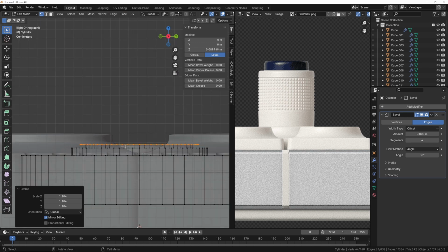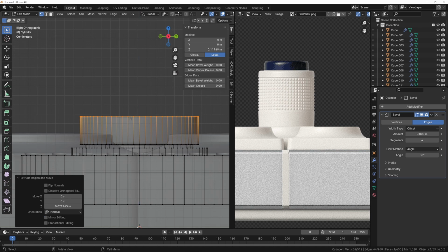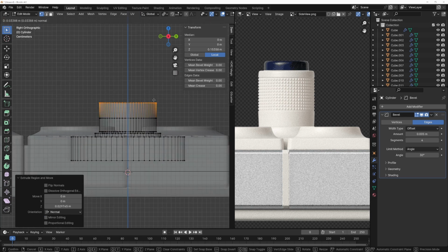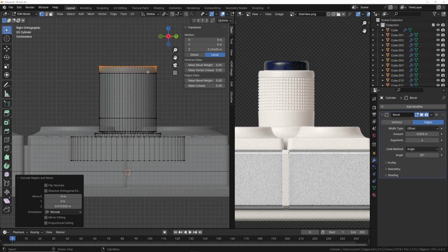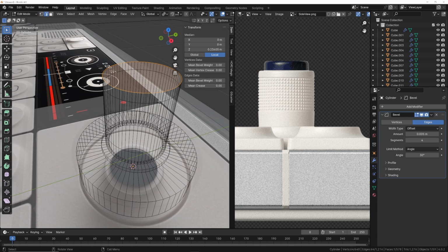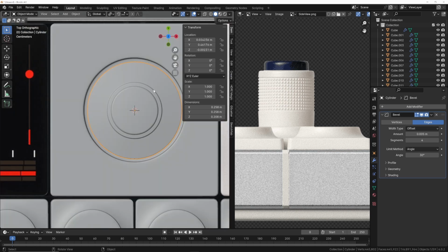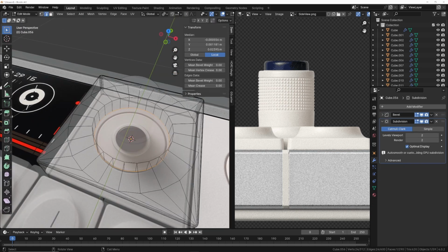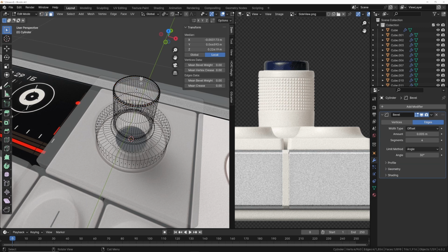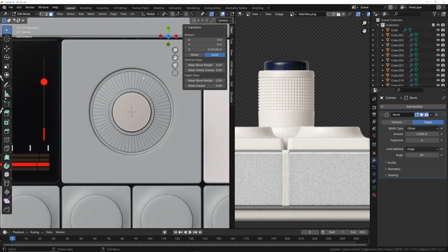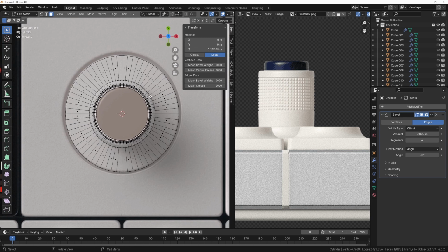Then we're just going to extrude this up, something like this, and then extrude upwards again. That's going to be that middle face right there. Extrude it up to make the top. We're going to do this manually. I'm going to click 2, Control B, or I could add X-ray, Control B, to make that top bevel the way it's supposed to be. Then we're going to go into Alt Z here, and grab the top face of this again, back into X-ray.